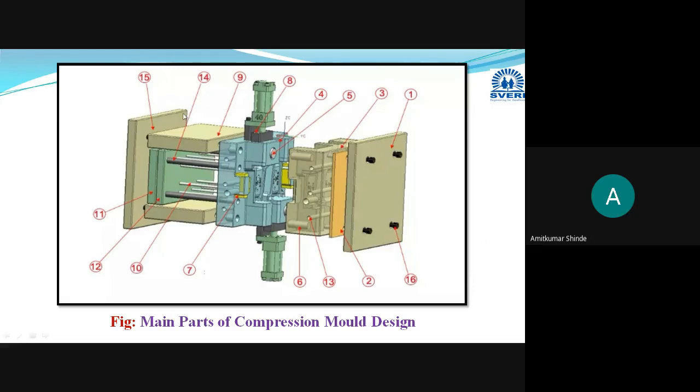These are the return pins or pushback pins. They will help the ejector pins come back to their initial position or home position. After ejecting the part, their position will be changed, and to come back to the initial stage, these return pins or pushback pins are used.